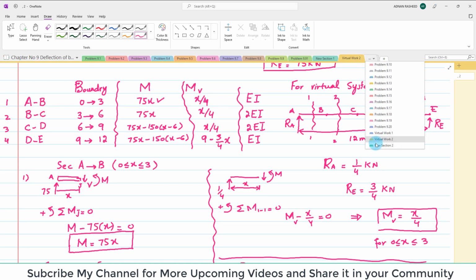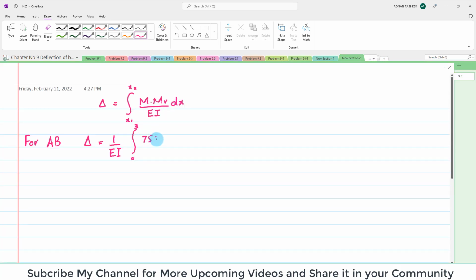So you can put 75x into x by 4 into dx. You also have the limit, so it will be equal to 1 over EI, and when you integrate from 0 to 3, it will be 75 x squared over 4 into dx, and upon taking the integration and putting the limits, you will get 168.75 over EI. So this is the deflection between point A and B.